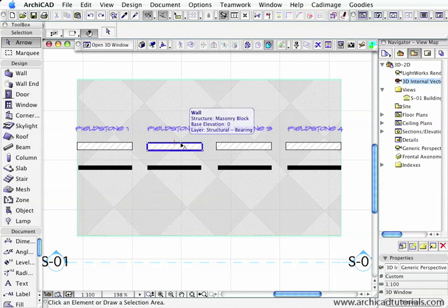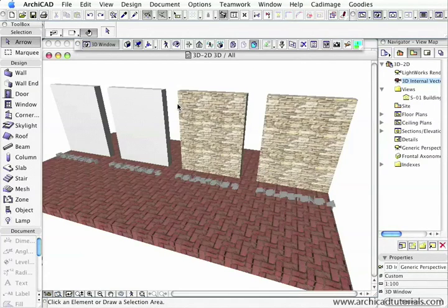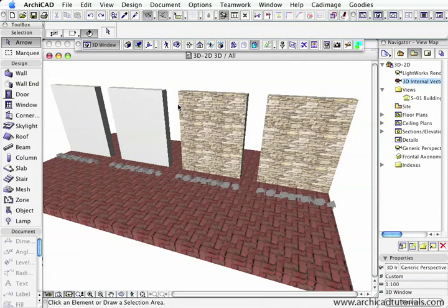This environment is really used to highlight the documentation aspect of the model: symbolic walls, roofs, windows, text and dimensions, etc. that help us deliver the paper plans that we deliver to site. The 3D view, so if I push F4 on a Mac and F5 on a PC, opens up the second environment. This is a perspective or axonometric view of the model. This is where we can actually view our model, analyze your design and change it as well. And because you're still in 3D, all the changes will be reflected through your model.